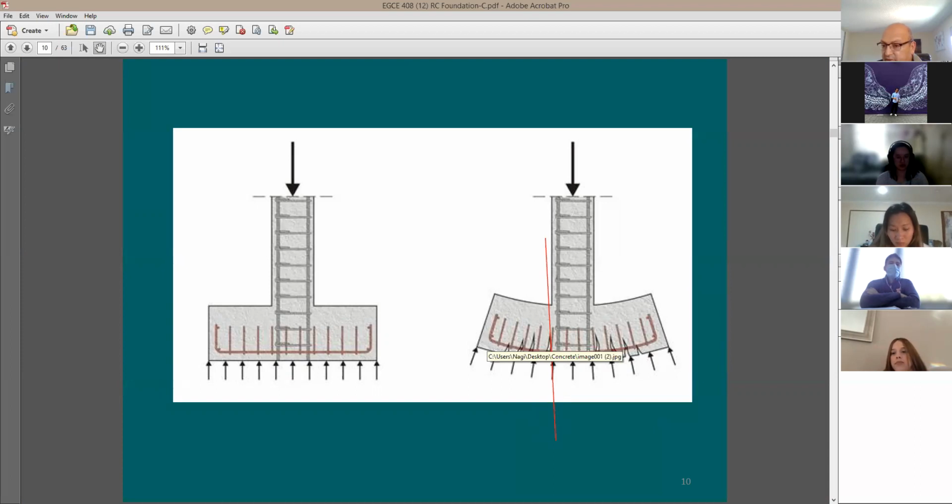And the pressure is going to be equal to this axial load divided by the contact area between the footing and the soil. So I can simply say this axial load is going to be equal to P, and the cross-section area of the pad, which means length times width, we're going to say area, which is A equals L times B. What is L?